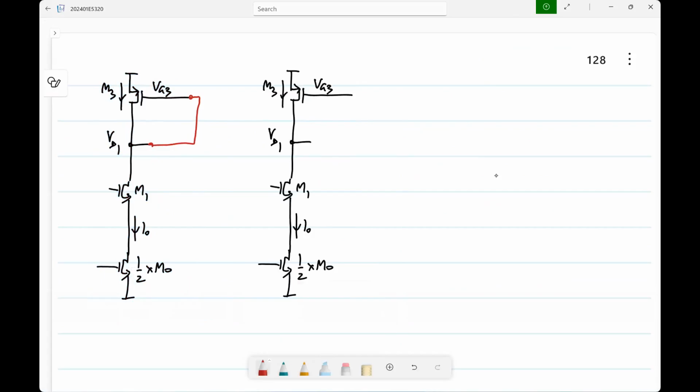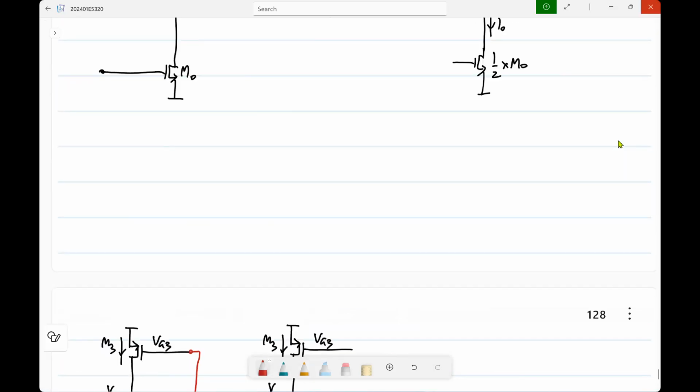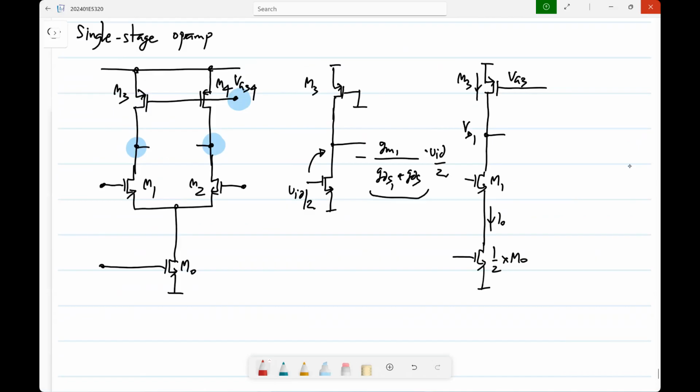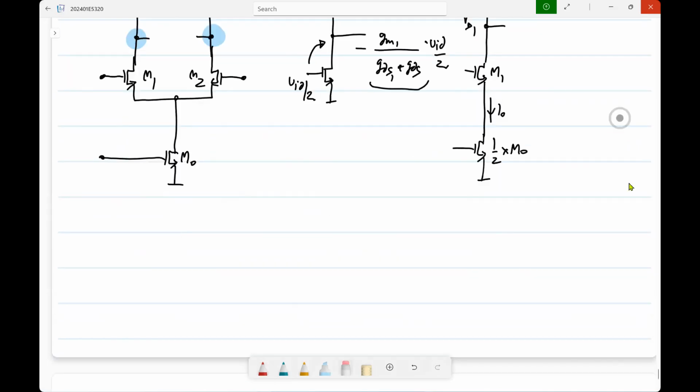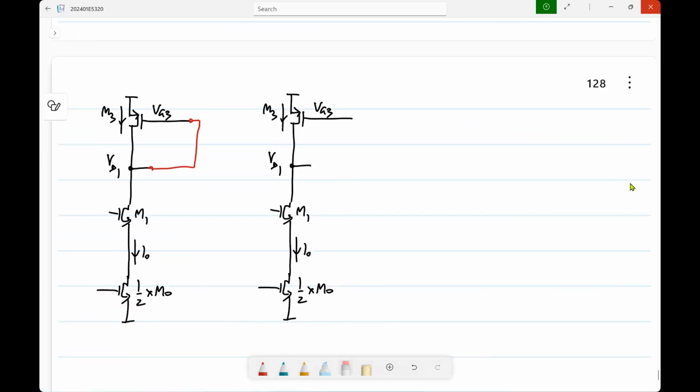You can do that. By the way, this is not complete. This will just take care of the common mode. Then you have to marry the differential picture with the common mode picture, right? So that in the differential picture, you get a high gain, and in the common mode picture, you get whatever you have to, so that you have a biasing point.